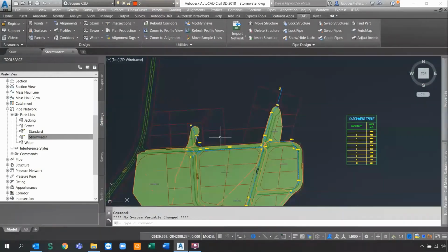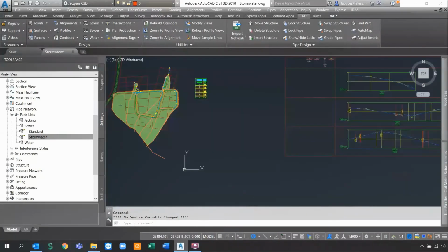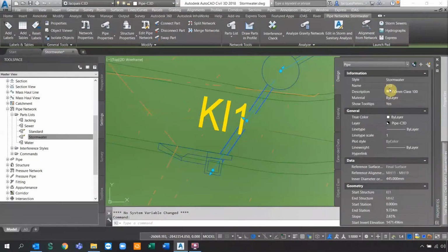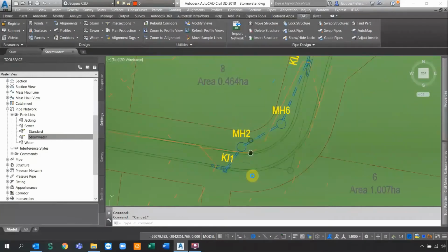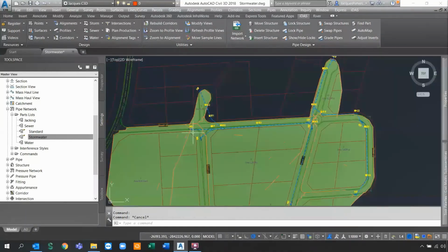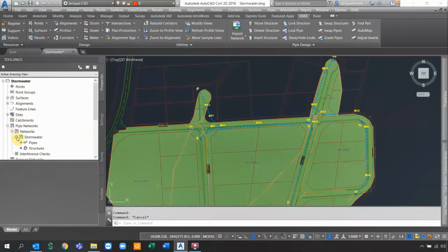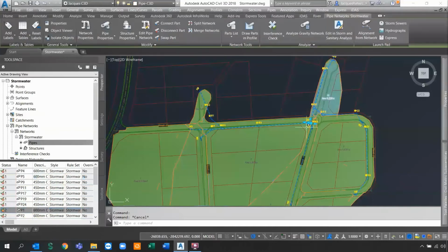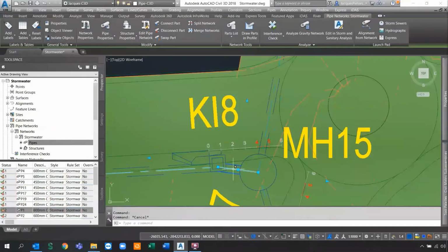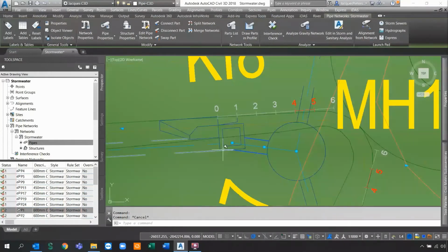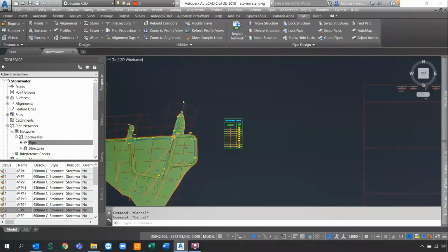And now if I'm back in Civil 3D, I can simply go and navigate to the elements. So let's see if those pipes have actually been updated. I think this is pipe 10. We're looking specifically for pipe 1 because I actually swapped that pipe. So the right way of finding pipes actually is if I go to my properties tab on the network stormwater pipes, then I can go and redefine them. There's the one. It says actually 600 millimeters, but let's say right click and select. There's my pipe number 1. So if I go to its properties, it also says it already automatically swapped that pipe for you. So you don't need to do that anymore.